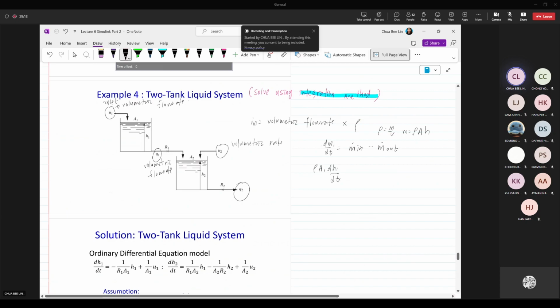Okay, then you continue the same for the rest, but you are going to actually stop when you get the dH1 side. You are not going to derive the steady state balance. For the previous transfer function solution, you use the unsteady state minus steady state, then you Laplace transform both sides. For the integration method, you just need to proceed with the ODE equation.